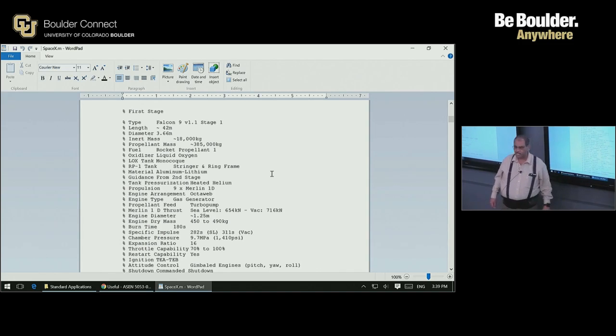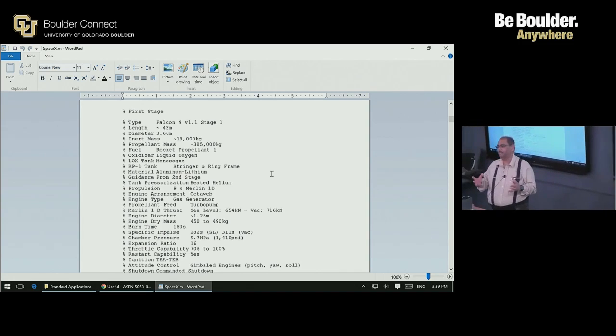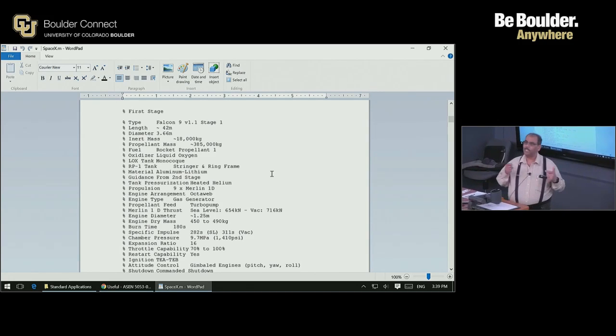Now, specific impulse. Specific impulse essentially is how good the engine is. Okay? In rocketry, we want to generate as much thrust as possible per unit mass flow rate of propellant, because the propellant mass is what we want to minimize. So the higher the specific impulse, the better. So definition is the thrust divided by the mass flow rate, normalized by using G naught. Okay? That is gravitational acceleration. Its value, of course, is 9.81 meter per second square, and the value used corresponds to the G value at the surface of Earth. Okay?